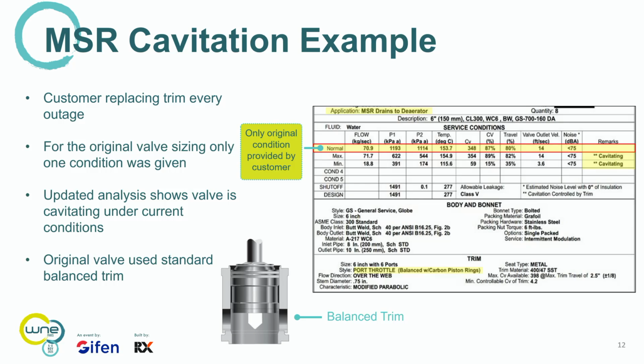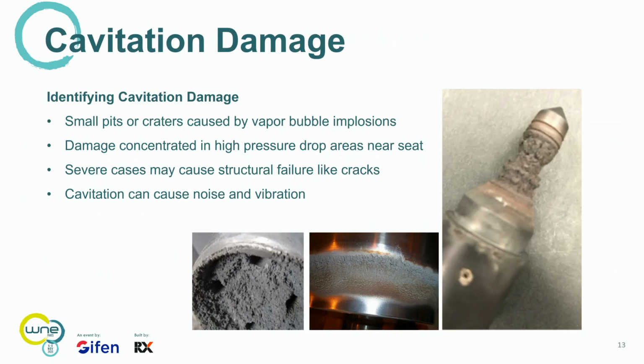Okay, so that's very key, whether you're building a new power plant or upgrading plants, to understand all the proper conditions the valve needs to operate under. Damage from cavitation is very severe, okay? That impingement, I don't care what material you make it out of. You can make it out of the hardest material. You can make it out of stellite, unobtainium, whatever you want to come up with, cavitation is going to damage it.